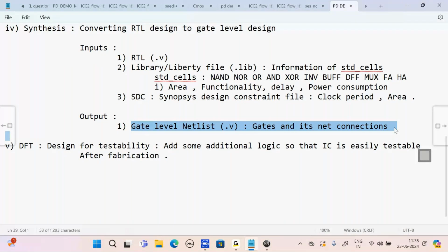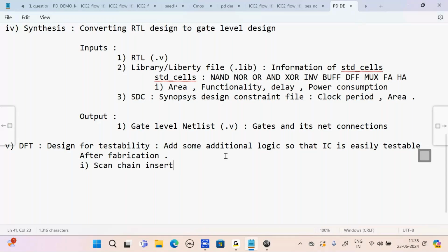So they will do some logic, I'll mention what they will do. They will do scan chain insertion. Next it is boundary scan. Yes, yes, yes. Area will increase obviously because some cells are added, right? Additional cells are added. So in the netlist, area gets increased.